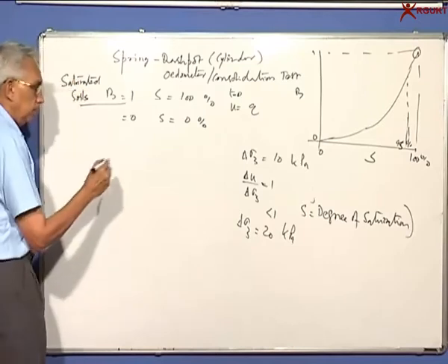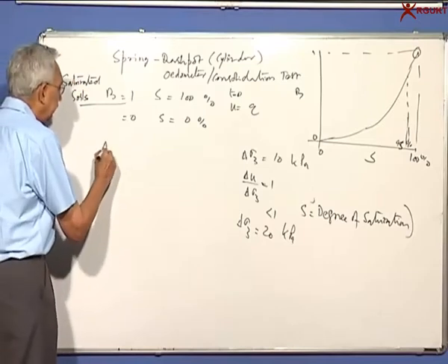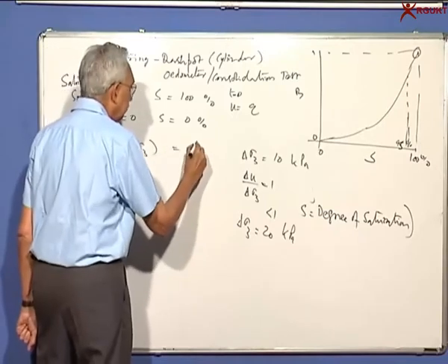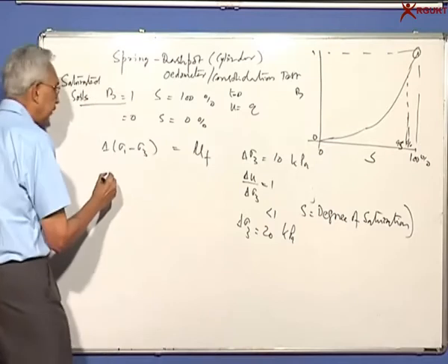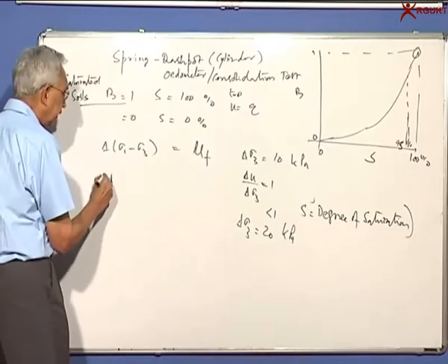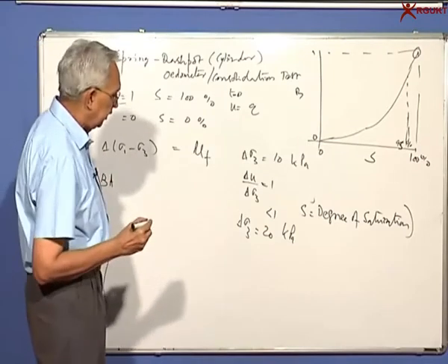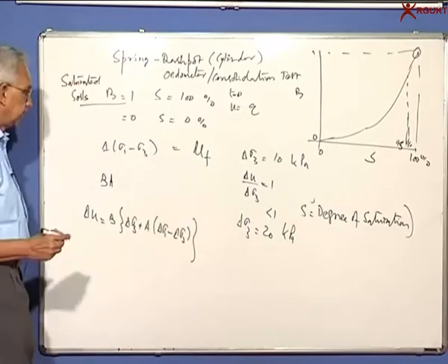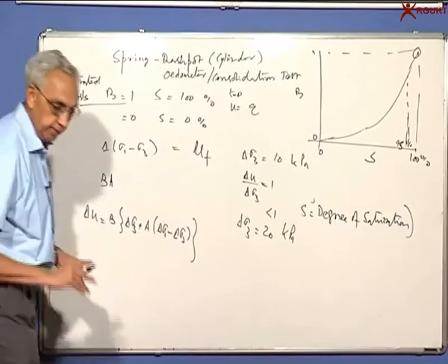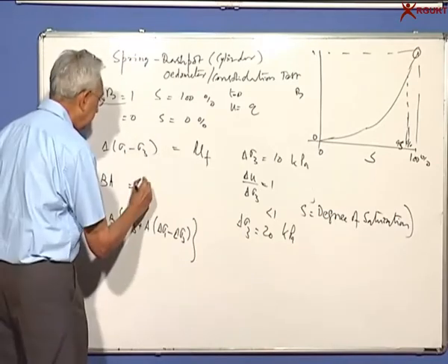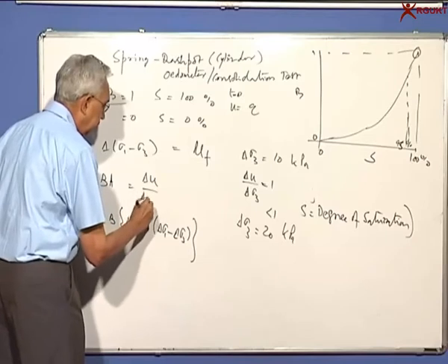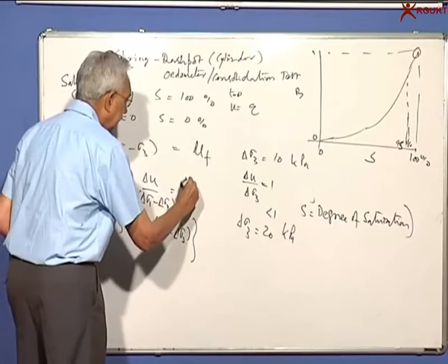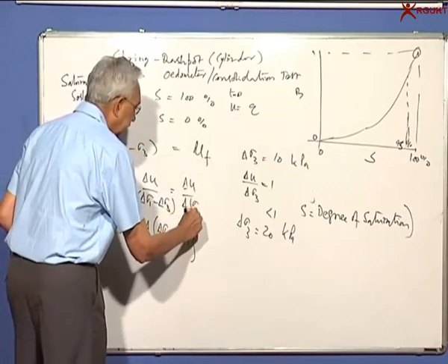Then, when you are applying delta sigma 1 minus sigma 3, and you are measuring pore pressure at failure, then A is equal to, actually, A into B. Where is our equation? We said delta U is equal to B into A into the deviatoric stress, so B into A is the pore pressure divided by delta sigma 1 minus delta sigma 3, the increment in the deviatoric stress.